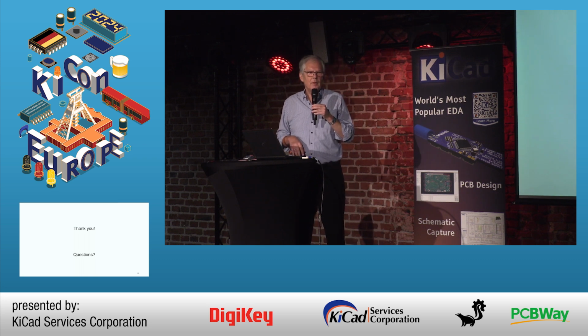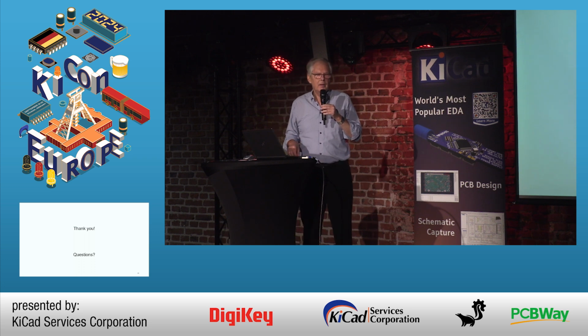What we have as a problem is we have a trace. We have a 200 millimeter trace that is half a millimeter wide. And then very fine if I can easily simulate the parasitics of my trace and of the ground plane, how it works together. And we are in the schematics, and then maybe there was a possibility to add a tool to extract the parasitics from my PCB, and then can I simulate that? Yeah, if you have this tool for extraction and you get the data, then you can simulate it.